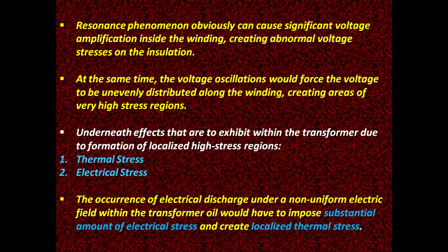The resonance phenomenon can cause significant voltage amplification inside the winding, creating abnormal voltage stresses on the insulation. At the same time, the voltage oscillations would force the voltage to be unevenly distributed along the winding, creating areas of very high stress regions.